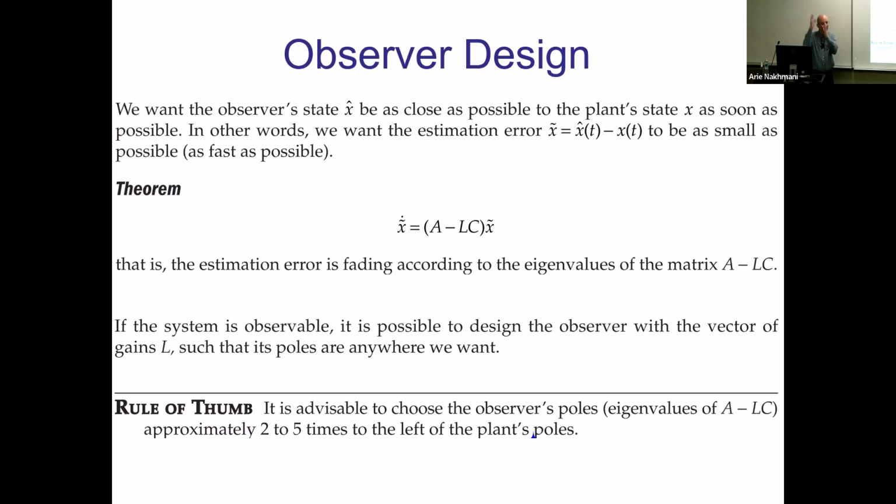And then you will try to jump fast to a new y, which is also noisy, right? So it will jump all over the place. These estimators will just change too fast. They will converge eventually, but they will be noisy. They will be jumping all over the place based on immediate y, okay? You want to give it some delay, some time to stabilize a little bit. So this is why you choose it like 2 to 5 times faster, but not super fast. Otherwise, it will jump to any noise it sees from the output y.